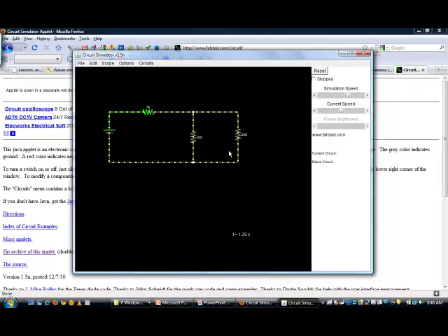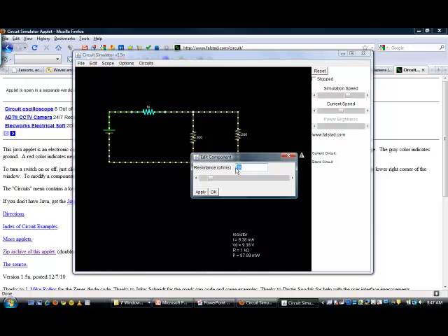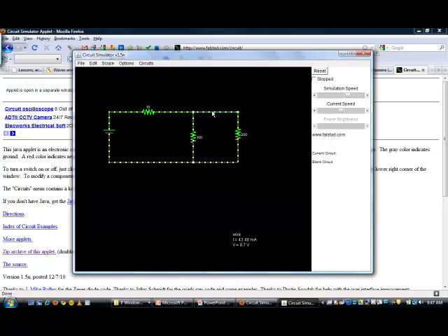Okay, the color resolution is not really that great, so it's difficult to see the difference between the color on top here and the color on the bottom here. But then here we have a voltage level of 625 millivolts, and here we have a voltage level of 0 volts. Now if this resistance here was smaller, we'll have a better resolution because the voltage change is going to be much larger. Let's make this just 10 ohms, and you'll see now here I have 8.7 volts and here is 0, and you see the color difference, and the whole thing changes.